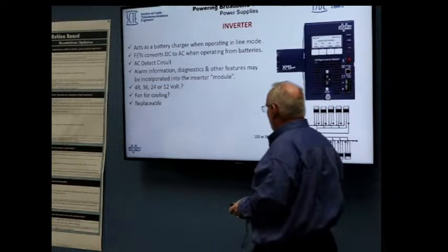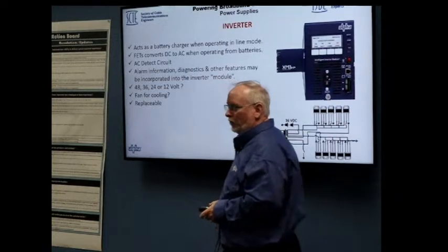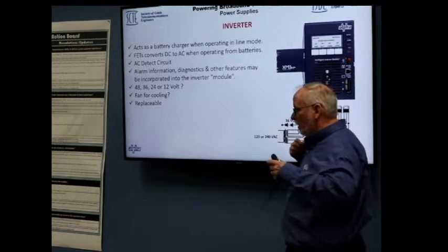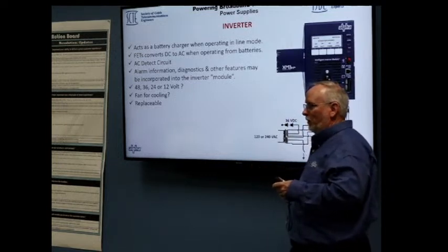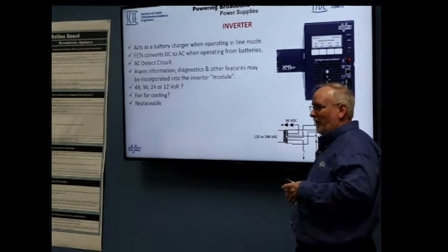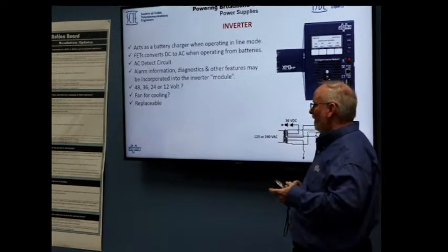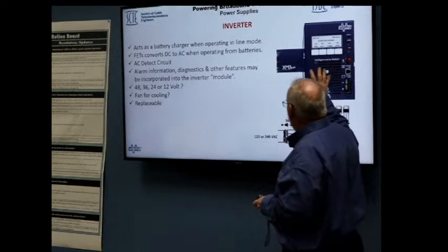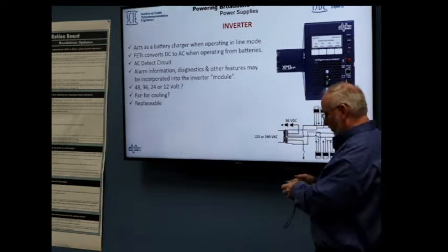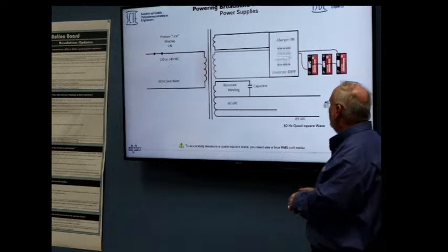One thing that's important is, what is the voltage of the system? If you take a 48 volt inverter and you slide it into a 36 volt power supply, it's not going to work. And if you do it the other way, into a 48 volt, things are not going to end well. So, you know, does it need a fan? Different things like that. There's a lot of considerations there.